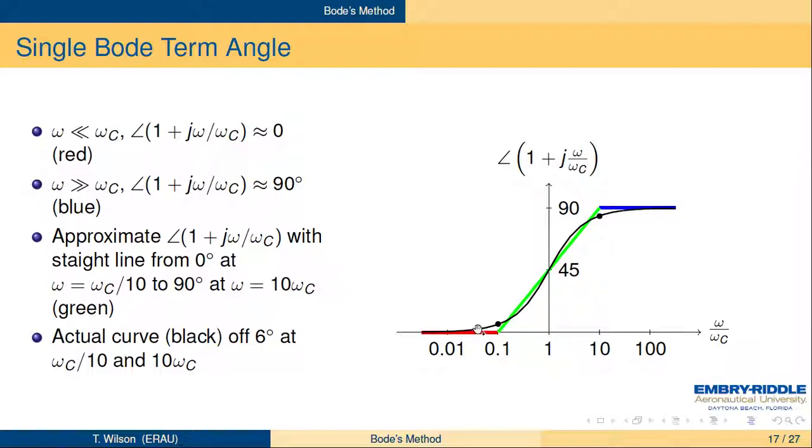You see it's a little bit funky compared to the gain curve because you're 6 degrees above, and then you actually want to go below the curve and go through the 45-degree point with a bigger slope than the actual straight line asymptote there, and then you come back through the 6-degree below, and then you're up to 90 degrees.